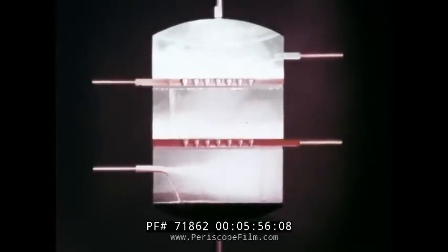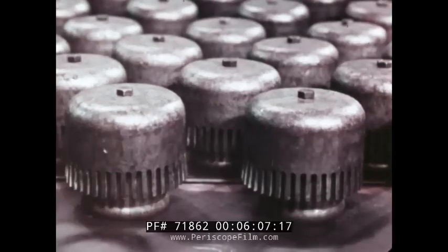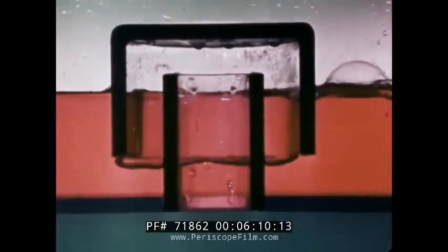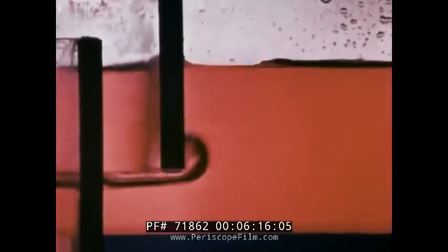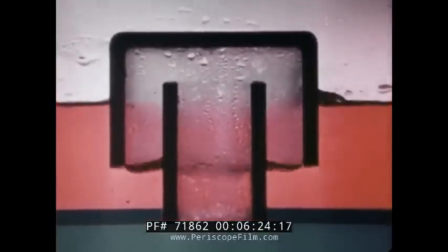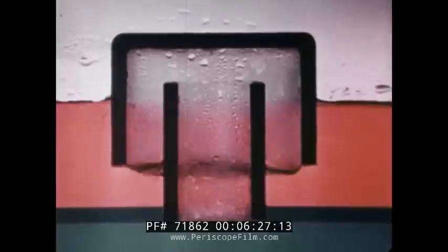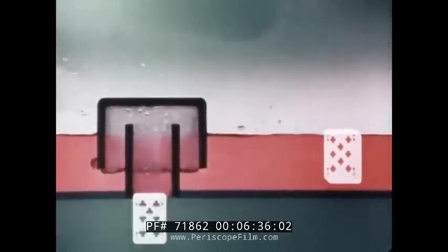There are several ways of separating the fractions. One way is to use bubble trays. On each tray inside the column are mushroom-shaped fittings called bubble caps. The hot vapors rise up through the stem and then back down underneath the bubble cap into contact with the liquid on the tray. If liquid and vapor are of the same fraction, the liquid will be cool enough to condense the vapor. Thus, if the liquid consists of 8s, the vapor that condenses will also be 8s.